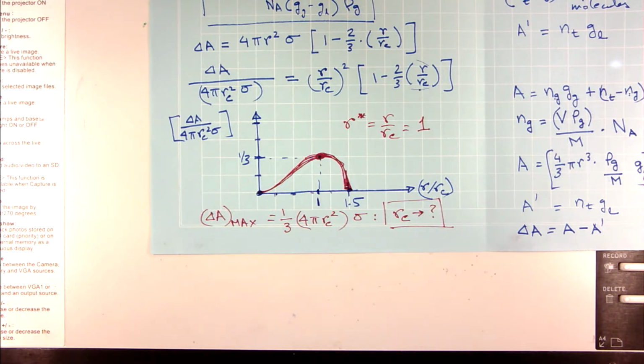So, now the question is, what is the value of R c? Okay, I know there is a critical radius. If I am below that critical radius, the vapor bubble will collapse, it will not be stable, and as long as my R is more than R c, my vapor bubble will survive. Okay. So, now if you look at this pool of liquid, let us say it is at a particular temperature, are all the molecules moving at the same speed? They are not, right.